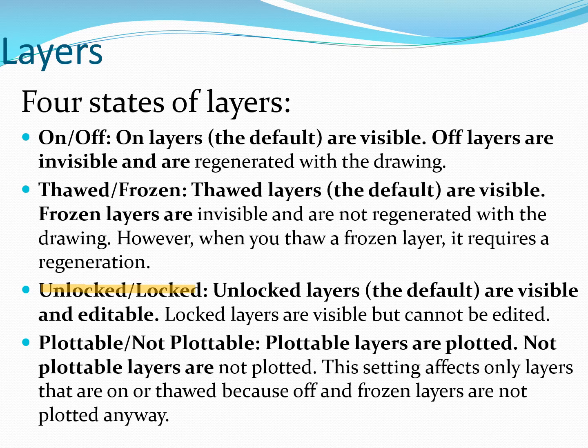Unlocked layers are visible and editable. Locked layers are visible but cannot be edited. Plottable or not plottable. This setting affects only layers that are on or thawed, because frozen layers are not plotted anyway.